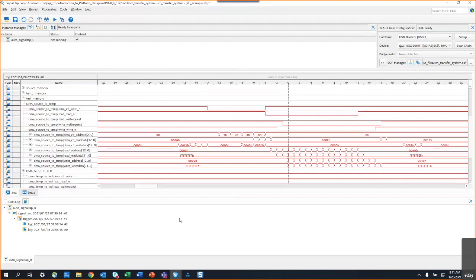Okay, so we have another question. This is a bit tougher. So this person uses a Python script executing on Windows to control their device under test and the connected Stratix 10 FPGA. Is there a way to shell a script that triggers a SignalTap trace and saves that trace to a file with timestamp or iteration number in the file? And this would be inside of a loop that their test keeps executing.